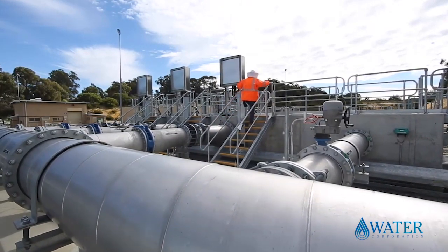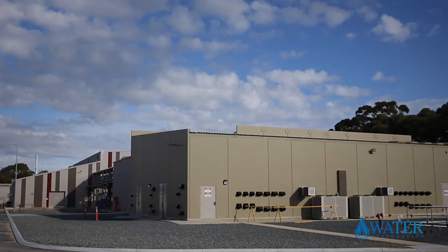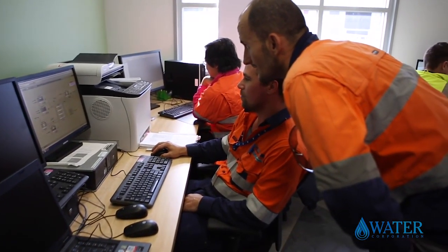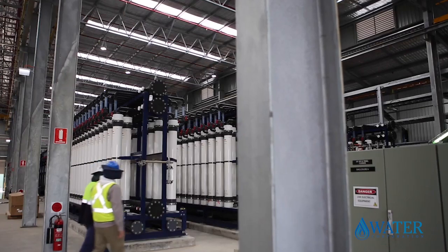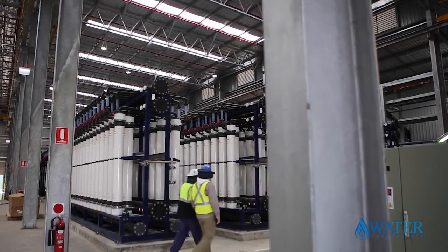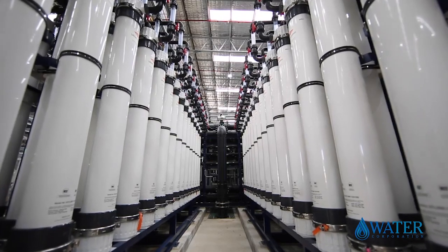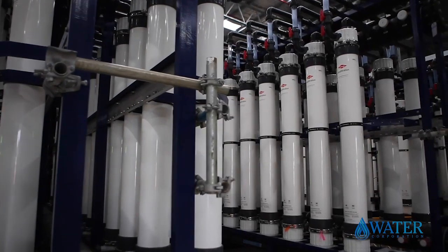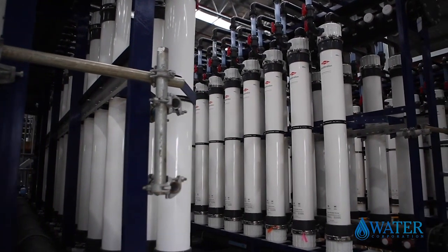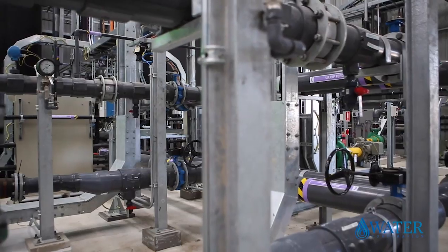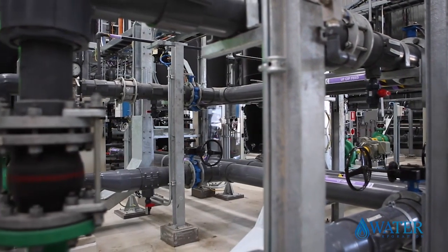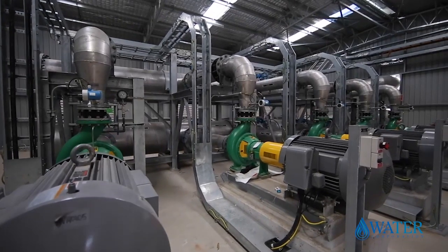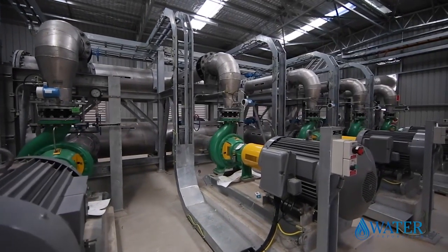An advanced water recycling plant was built at the plant site, supplied with secondary treated water from the wastewater treatment plant. The plant treats the water to drinking quality standards using a 3-step process: ultrafiltration, reverse osmosis, and ultraviolet treatment. 13 critical control points are positioned in the treatment process to monitor the quality of water passing through and safeguard water that does not meet standards from progressing. New recharge and monitoring bores were also built.